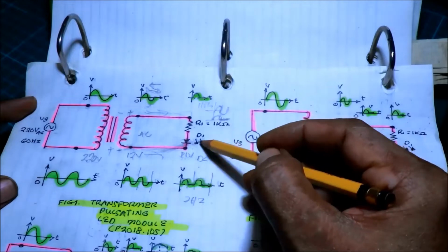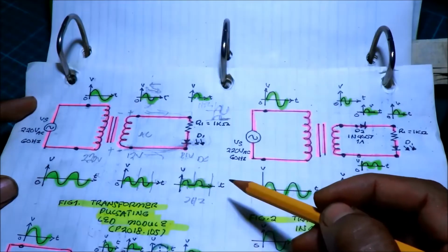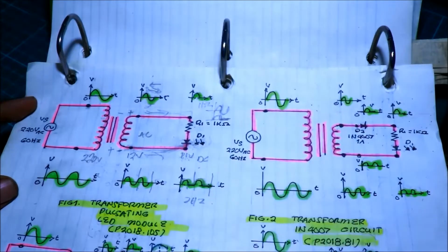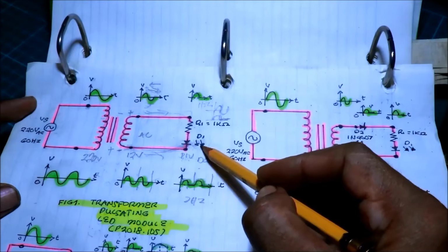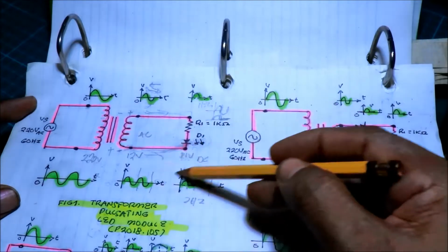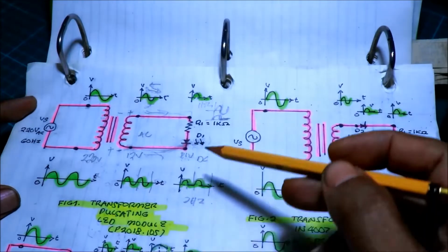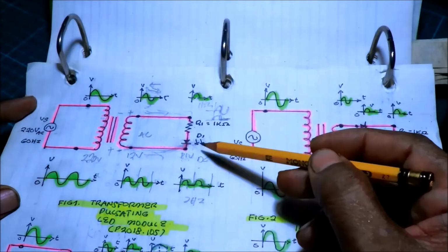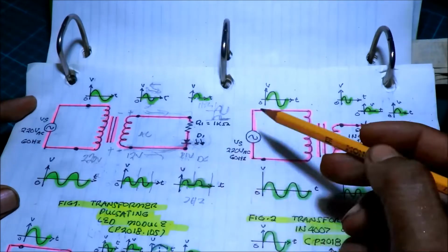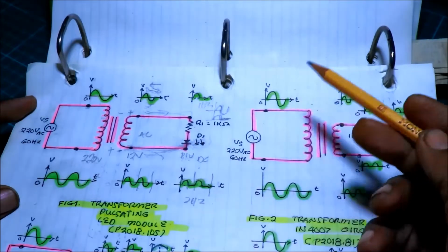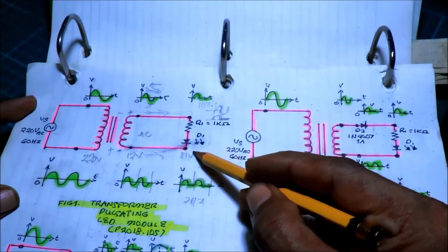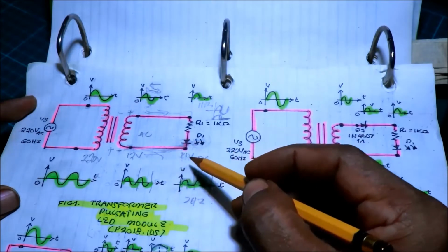So we have a special type of diode we can use to protect the LED, and that's why I constructed another circuit. And before that, because of this transformer pulsating LED module, we know that the LED is pulsating or blinking. What kind of circuit have we already constructed? This is a half wave rectifier, but it is an unadvisable half wave rectifier,